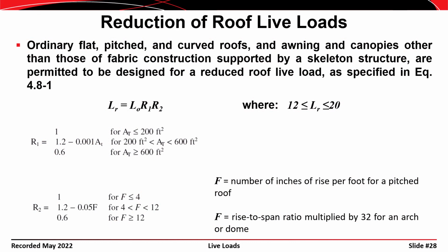You're allowed to reduce the live loads on a roof like you are the live loads on a floor. However, the equations that we use for reducing roof live loads are a bit different than those that we use for reducing floor live loads. Those are presented here, and they'll be illustrated in some example problems.